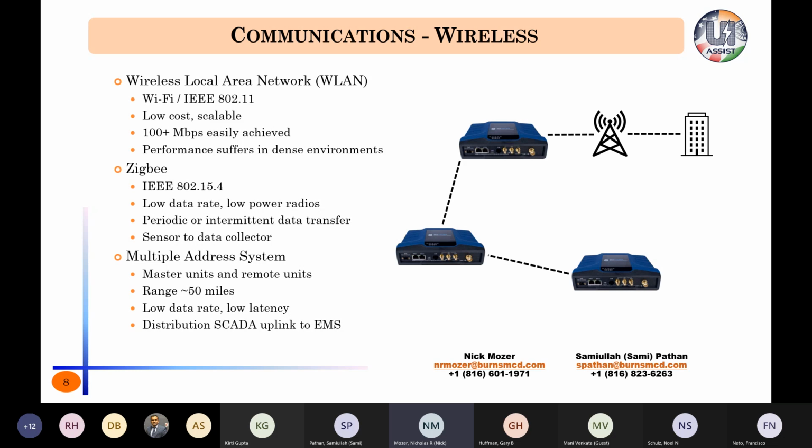Looking at some other options that we have here, like Zigbee, this is a pretty low cost technology that's often used in personal area networks, for example, in a home energy monitoring system. They're low cost because they're low power, so they don't output very much, and in turn, that means that there's not a lot of distance you can get between these. It's about 100 meters or so, but because it's low power, you also get a long battery life. So there's a little bit of a trade-off here, and depending on the type of application, this is where you might consider Zigbee versus Wi-Fi.